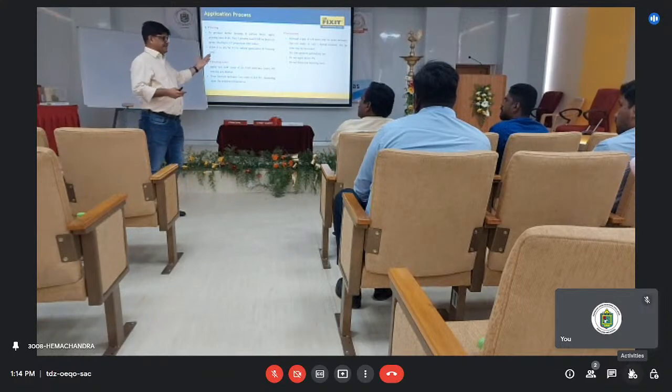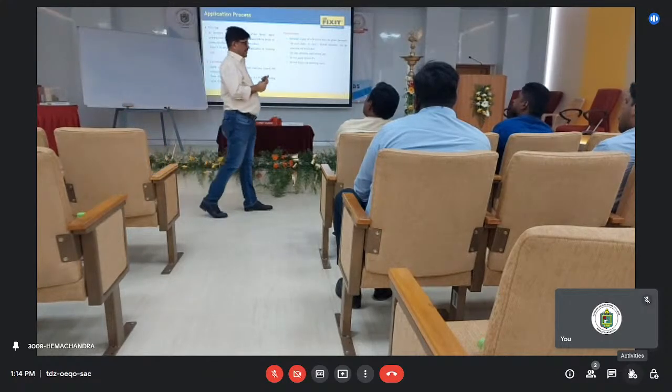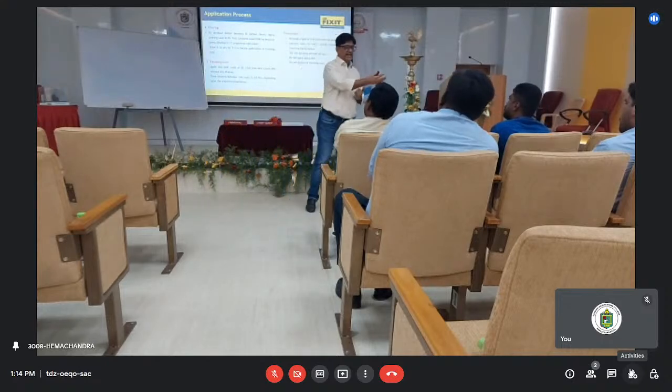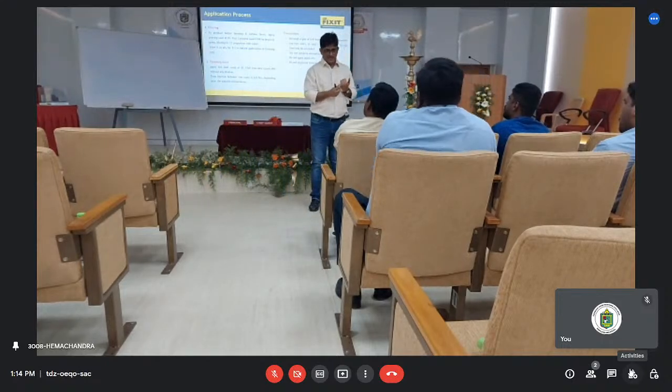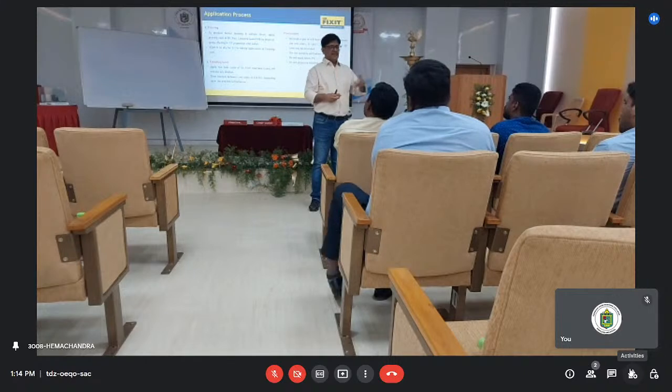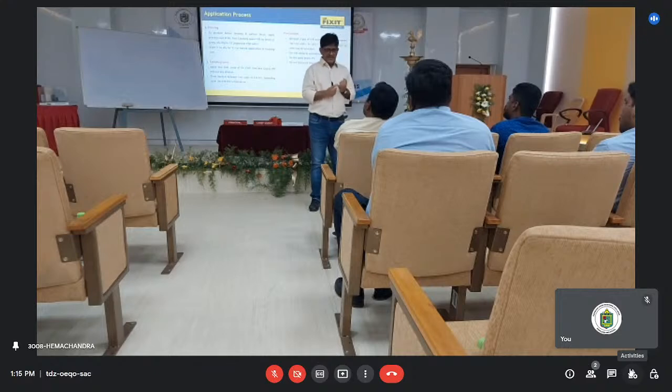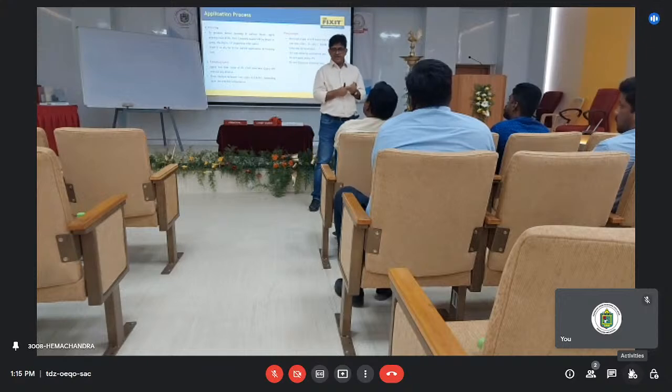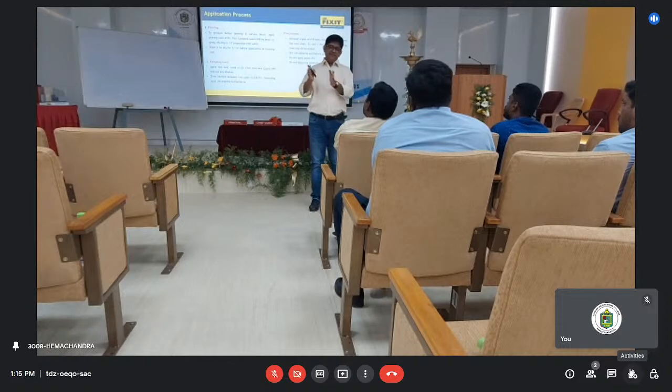But see, if you are going with a good quality weather-resistant coating, like the Dr. Fixit Raincoat system, I'm giving you an example, other Asian Paints products also have them, a good quality weatherproof coating system gives you some bit of anti-carbonation resistance. But anti-carbonation coating has a different chemistry, so not every coating has it. Raincoat has an anti-carbonation facility, we have built it up.